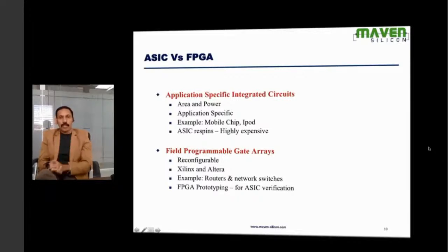What I'm trying to do is generate a lot of real-time scenarios and verify my design on the actual hardware. I would even be able to connect a lot of real-time peripheral devices with my chip and do a lot of experiments. This gives me confidence. I can fix bugs even in the software also. This is called FPGA prototyping. That's where FPGAs have been used extensively.